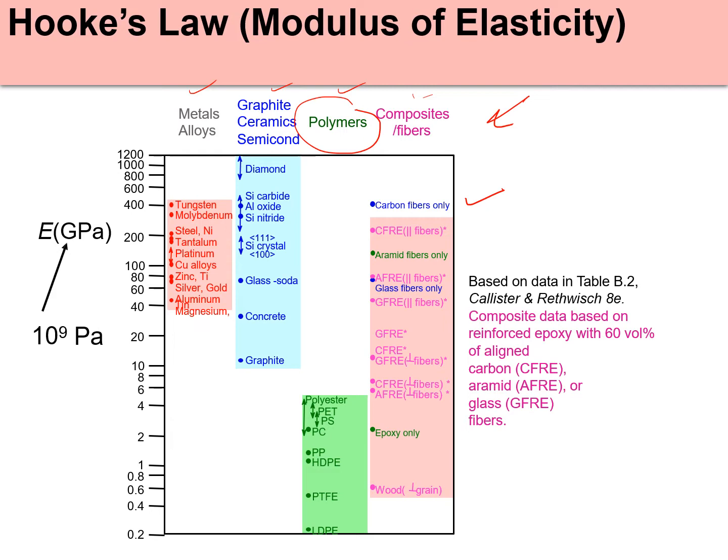For the modulus of the ceramics, it's quite high. You can see it's quite high, generally up to 400 or more than 410 gigapascals. This is because the strength of the ionic and also covalent bonds makes the modulus higher compared to the other groups of materials.